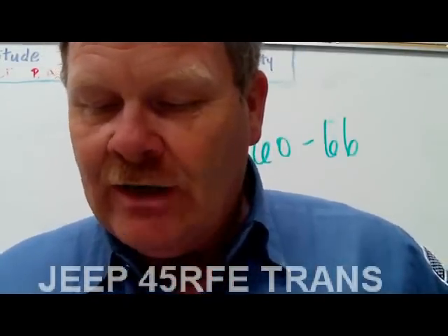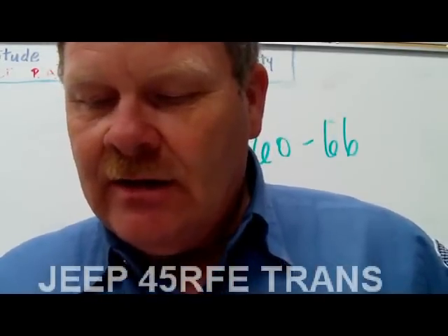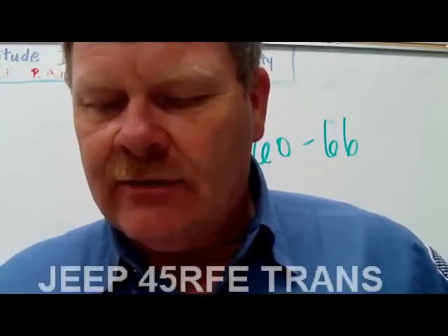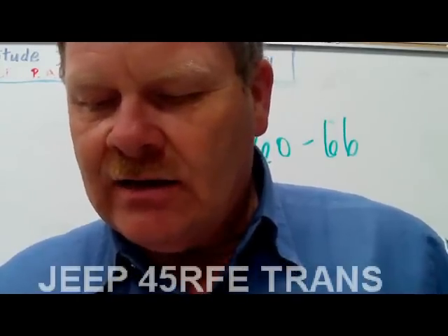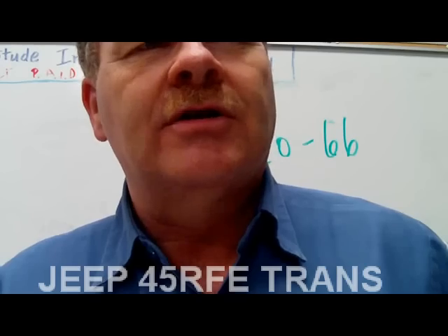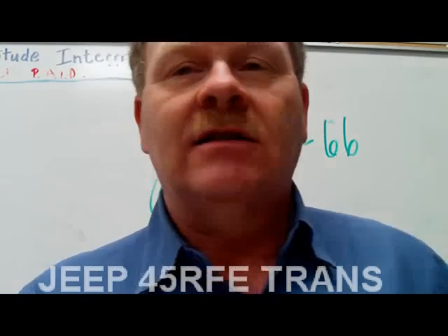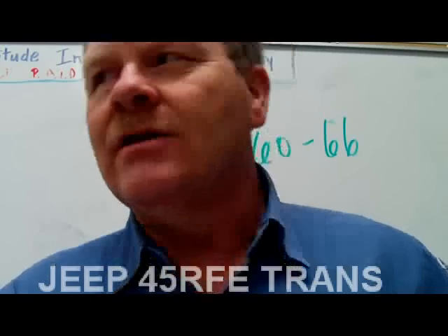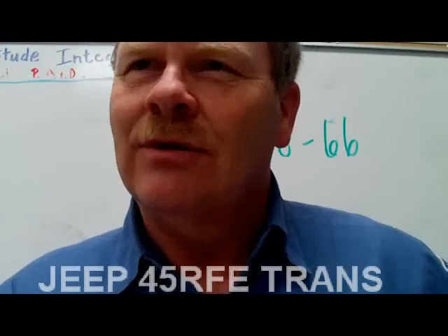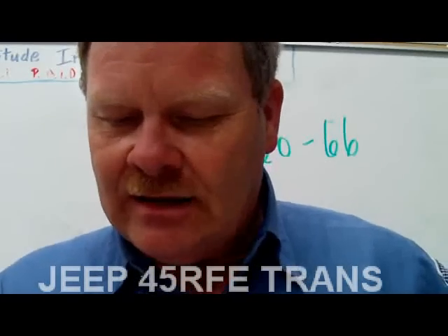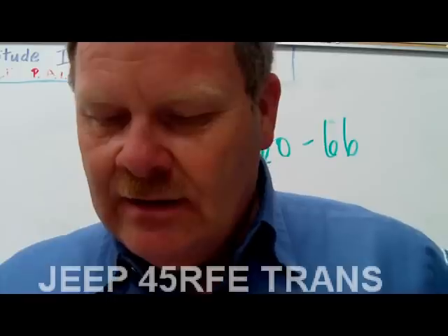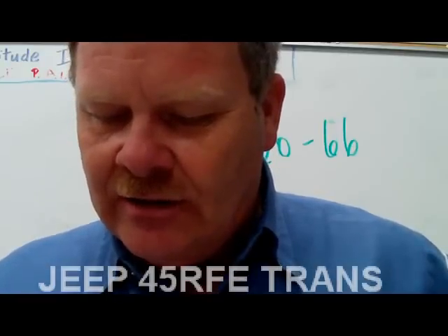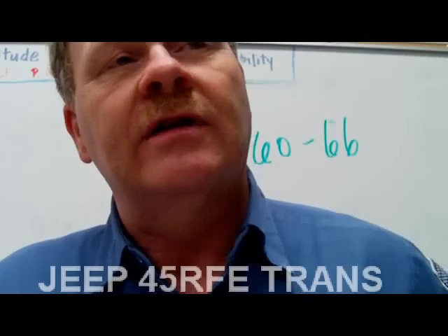And it's fully adaptive. Now, what does that mean? The control module calibration learns to compensate for differences in hardware. Basically it learns. A lot of these automatic transmissions learn how you drive, and it changes the way it handles its pressures and all that. That's one of the things they can do with all this heavy-duty electronics. It employs an engine torque management strategy during high throttle shifts, and that results in smoother, quicker shifts.